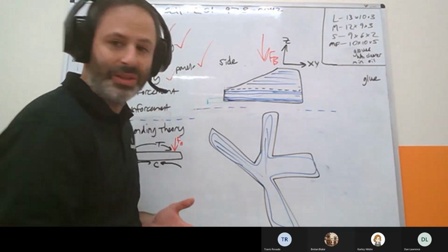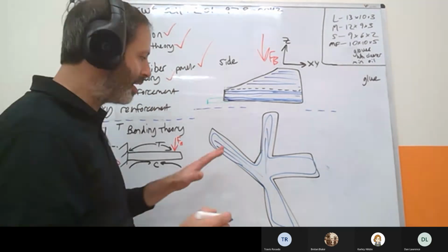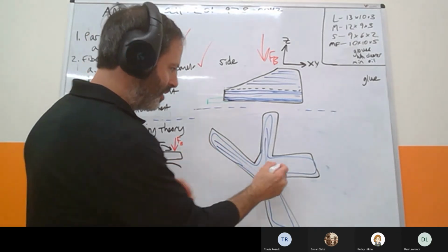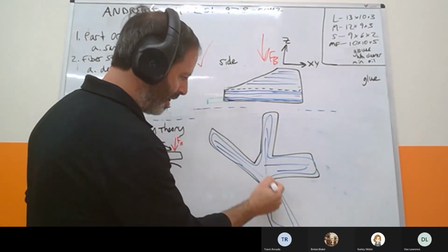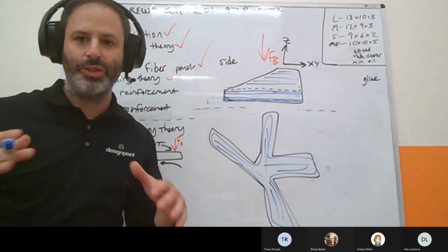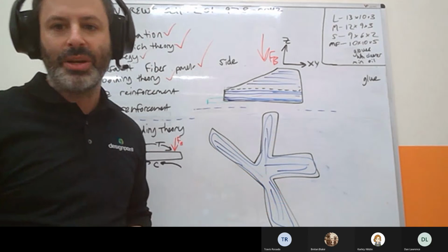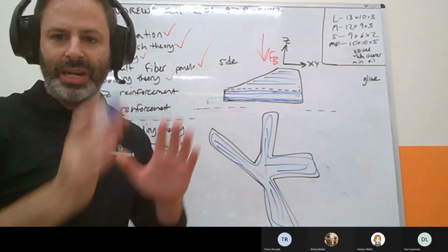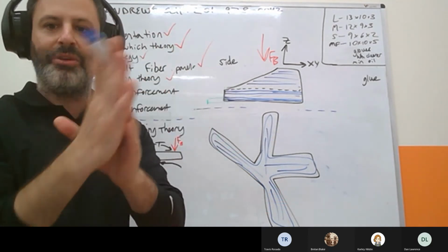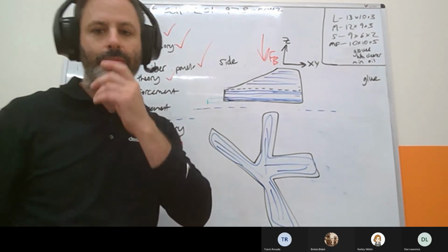And of course, it couldn't be on every layer, but you could have one layer where it supports this section, one layer where you've got fiber going that way, and different layers where you're sending your fiber off in different directions. It would have to be on separate layers though, but you can align the isotropic fiber fill in any direction that you want.